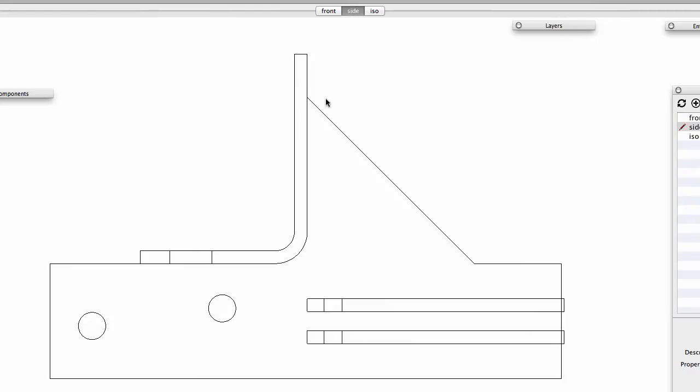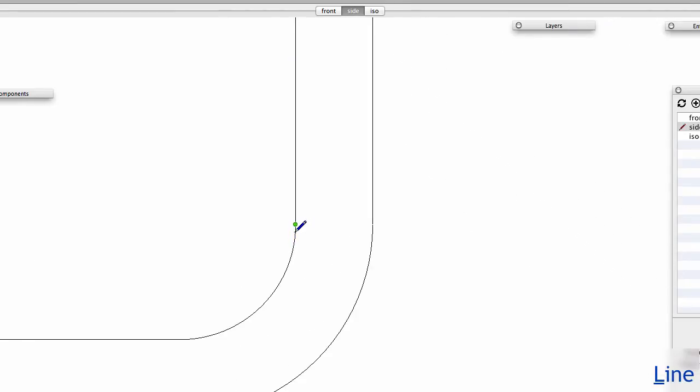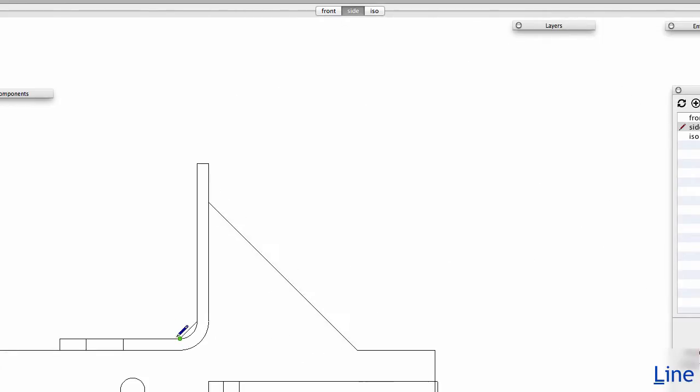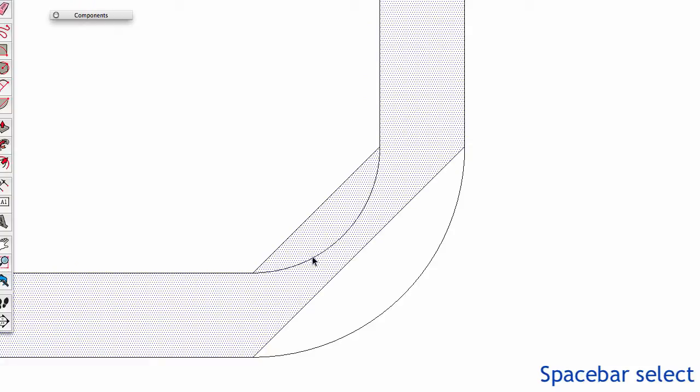Click on the side view, L to start drawing a line. And when you're working with CAD, I find that endpoint works great because you can snap to endpoints, but circles and arcs come in way too detailed. So what I'm going to do is pull along the line until I hit the first endpoint I find. That way I've isolated the arc geometry from the CAD. Do the same here. Come down, first endpoint, click back over. Now I can resolve the arcs.